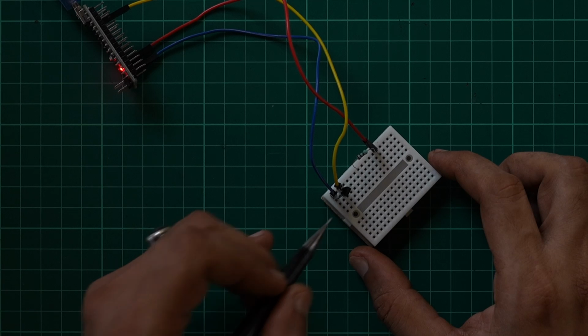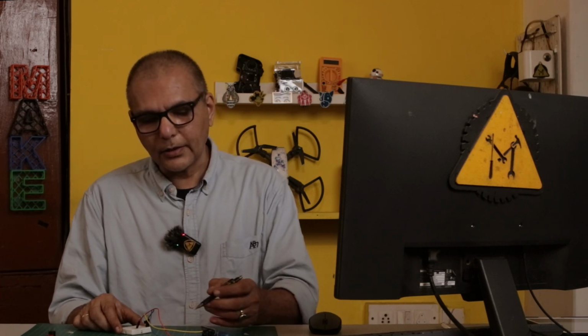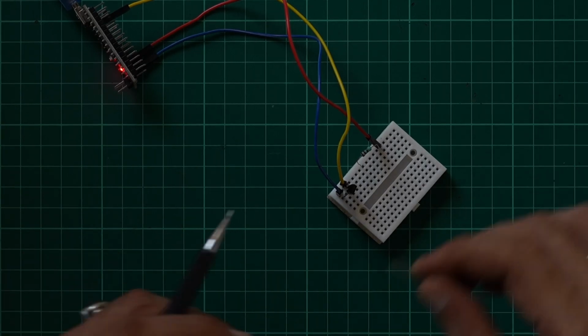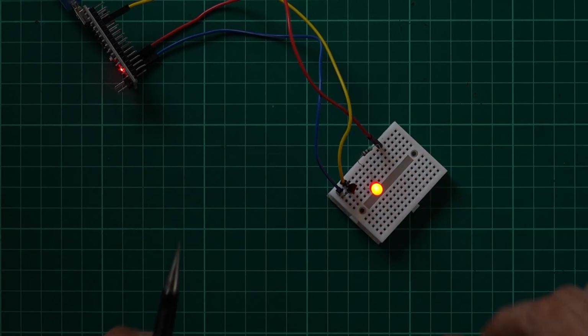So once you have a transistor, you can think of it like an amplifier, something that requires a small amount of current on its input, and that allows you to control a large load like a relay. If you have something like a relay, you basically want on and off control, so there's really not much control. But using a transistor, you can also use it as an amplifier, where you can apply different levels of voltages, or you can control the current flowing through the load by adjusting how the base signal is applied. In this case, that's exactly what we're doing. We're changing the signal coming into the base, and that helps us adjust the intensity of the LED or the sound output of the buzzer.